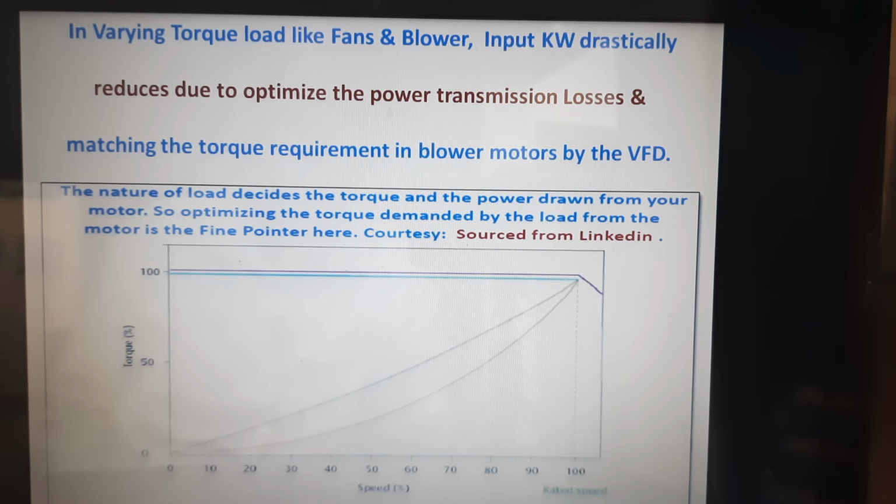of these utilities follow the affinity laws, and they have excellent scope for energy saving if the RPM of the machine is optimized, and the energy influencing parameters like the static Pascal and the flow from or to the machine, either a suction or delivery blower, are optimized. Definitely we can see excellent energy saving here. But mandatorily the VFD becomes a retrofit for all the blower systems in the plant as such.